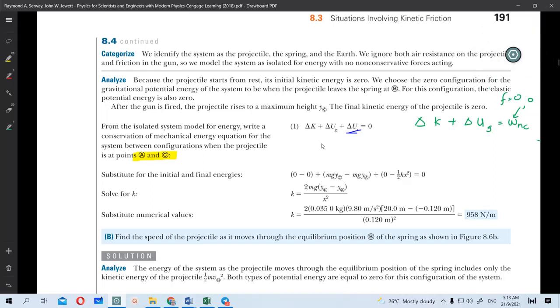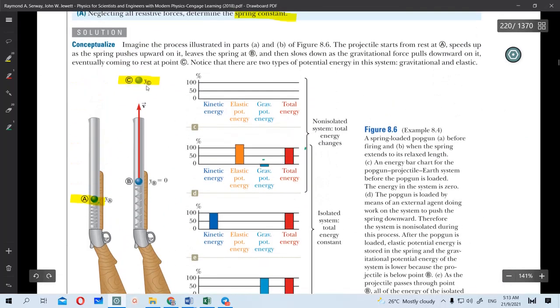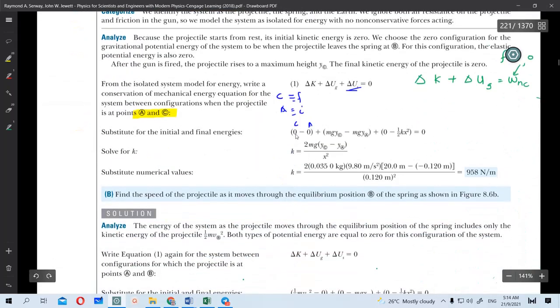Now, adding the spring is nothing special. So you will find that C is now our final, and A will be our initial. Okay. The change in kinetic energy: kinetic energy at C minus kinetic energy at A. Okay, we look at C and A. Now, at position C, V will be 0. Remember the idea of turning back earlier when it reaches maximum height? Okay. So here it's static, because it doesn't move. We push it and let it stay there, and only then do we pull the trigger. So here its U is also zero. So that's the reason why the energy change is 0.